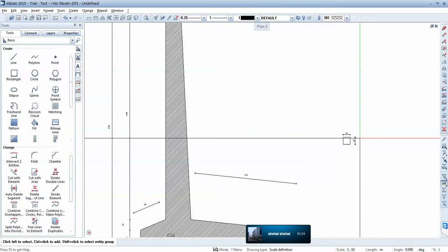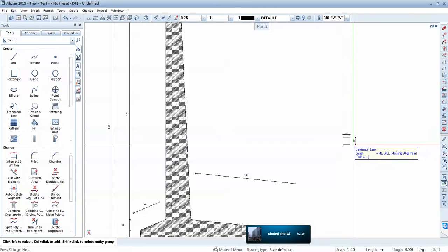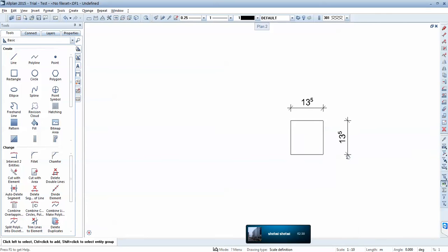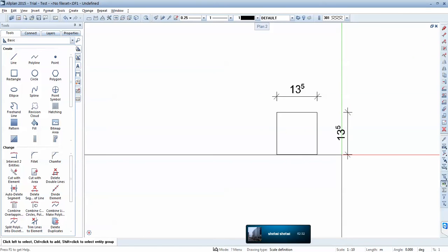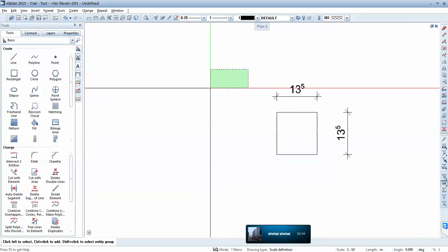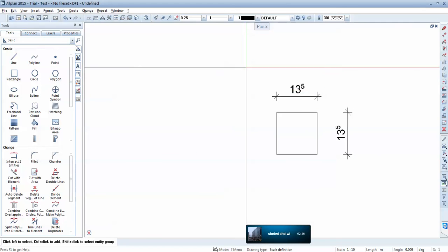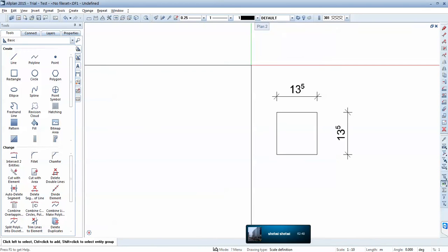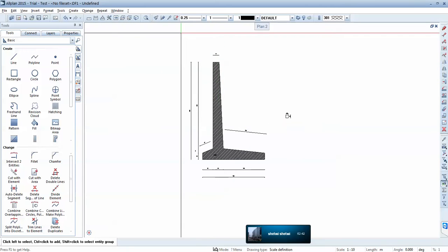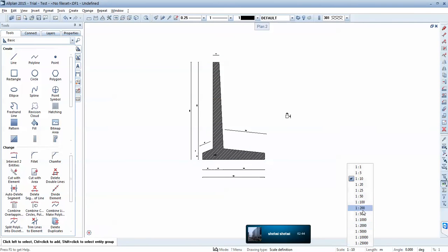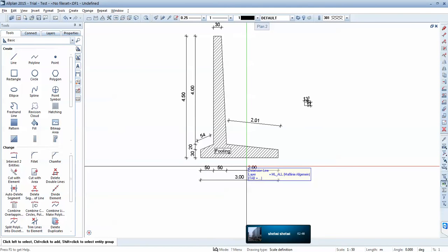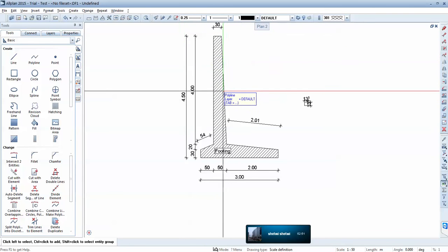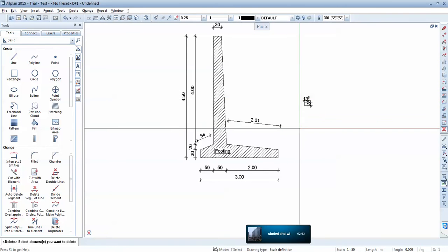The thing is, I'm drawing it one by one. I don't use any scaling factor. However, when we'll do the layouts for printing, I will do some drawing, exactly like in AutoCAD, some viewports, and I'll say I want this detail 1 by 10, and I want this detail 1 by 50. So in the end, they will look perfectly. Both will have the same dimension for text and will have the correct dimension on paper.